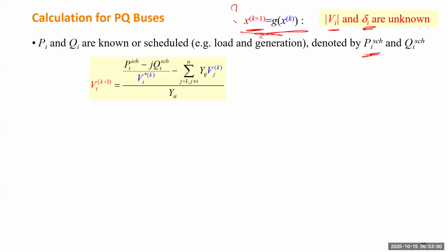The generation dispatch is going to solve a more general power flow analysis problem. You have some room to adjust between the lower limit and upper limit for each generation. So by that section, we'll be able to know the scheduled value for each generator. But in this section, in power flow analysis, we assume the PQ is already known for the load.